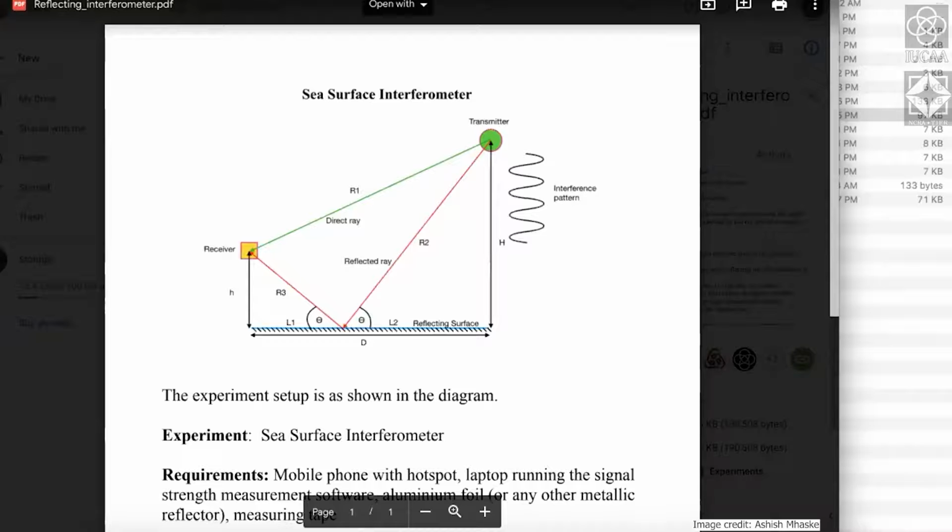And so in order to avoid a prominent role of those kinds of reflections in your experiments, which are meant for studying something else, it is recommended that you keep both your transmitter and receiver at a certain height, so that there is no prominent reflection and the direct path power dominates.